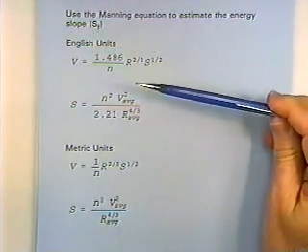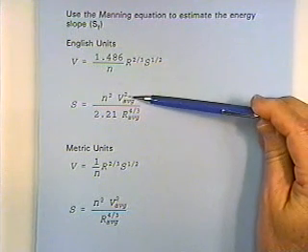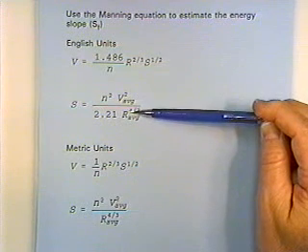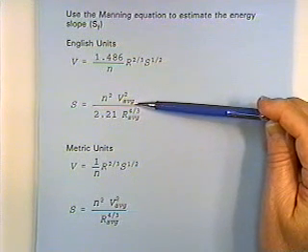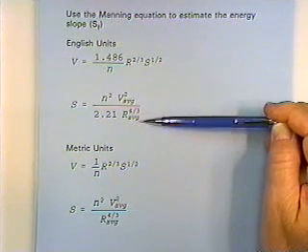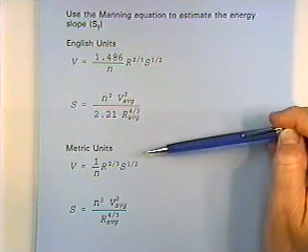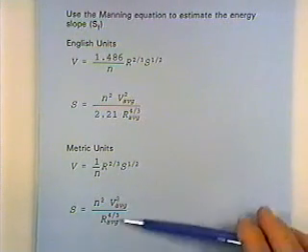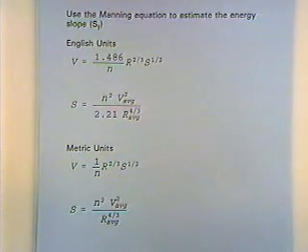And the thing is, what velocity do we use? The velocity is different upstream and downstream. What hydraulic radius do we use? It's different upstream and downstream. Well, we'll approximate the velocity as the average velocity, just the average of the upstream and downstream, and average the hydraulic radius upstream and downstream, and use the subscript average for that. If we wanted to do this in metric units, it's the same thing, just the constants are different.